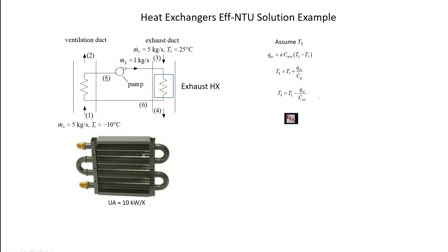And when I get back to here, I'm going to find that the T5 I guessed isn't right, so then I can adjust, right? So that's the typical thing you have to do in any energy system: start someplace, make a guess, and then work your way through the entire cycle and get back to where you started from. And that's how you close up that guess.